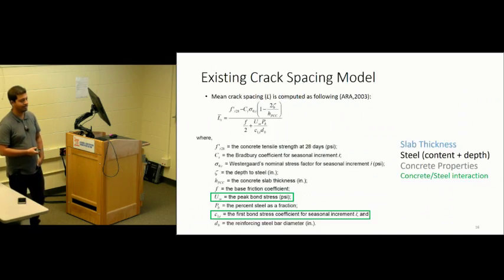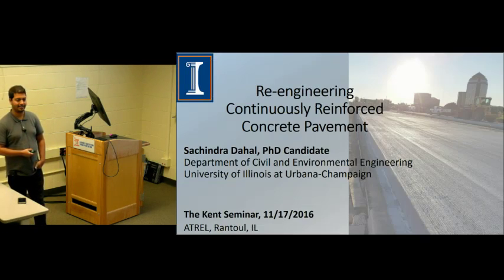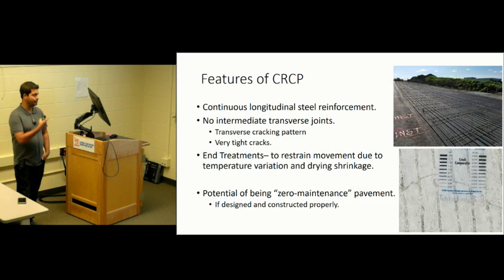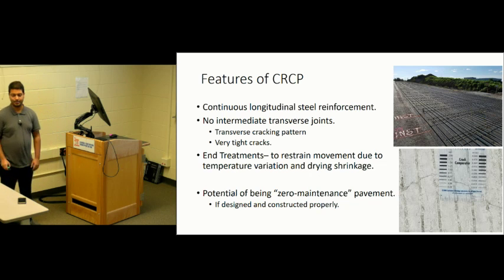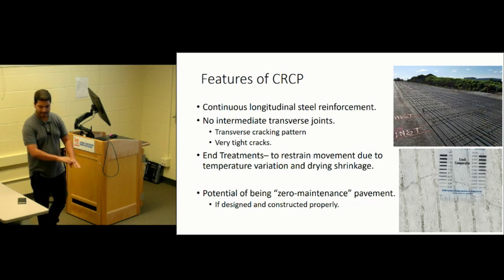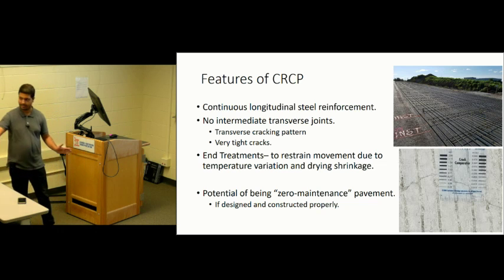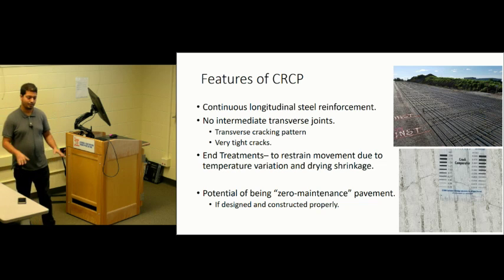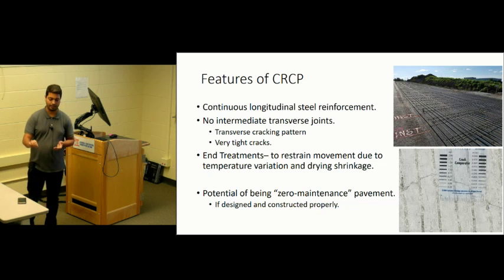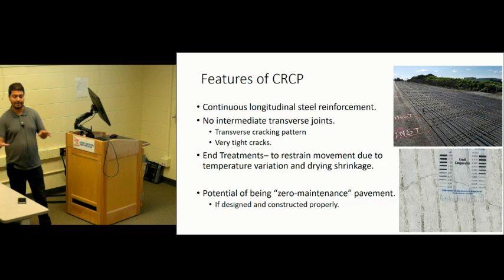That's when I thought you were doing this with one of the fancy sensors. Okay. No. So we manually measure the crack width. So it's the most subjective part. Because we have 200, 300 cracks that we have to go and manually measure. And the crack width changes on different segments of the lane. Usually crack widths are wider towards the edges and start getting smaller in the middle. So we find a location that approximately represents the overall crack width, go there, and measure the crack width.